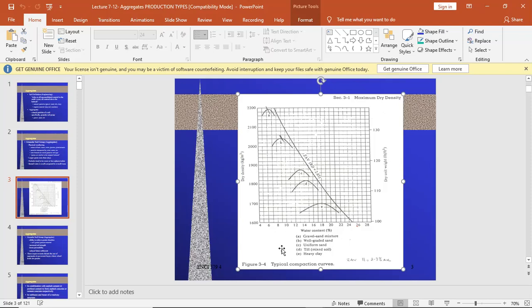Then there is the problem of honeycombing. As we know, in cement concrete, if there are more voids, then it is very easily breakable. When we use aggregate, we talk about every size of aggregate being there, but in some proportion.